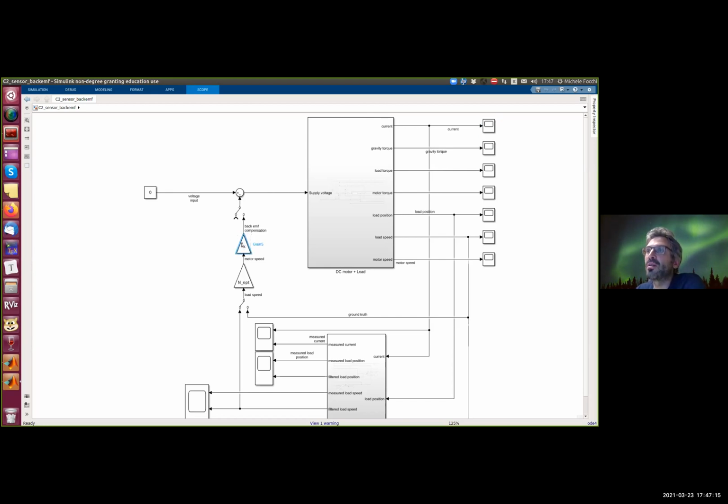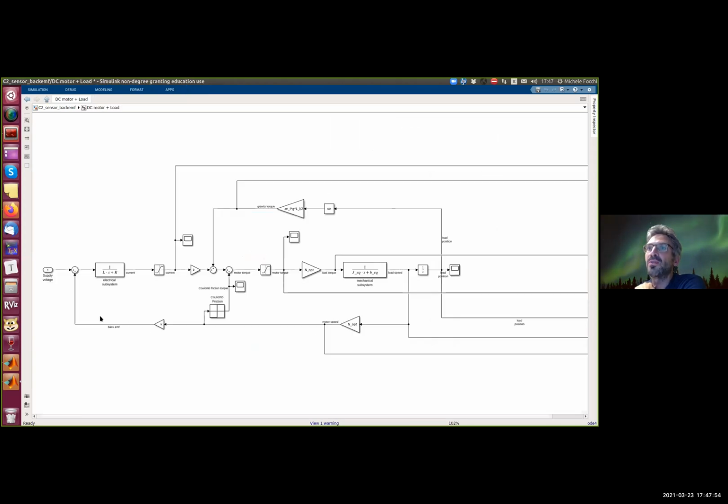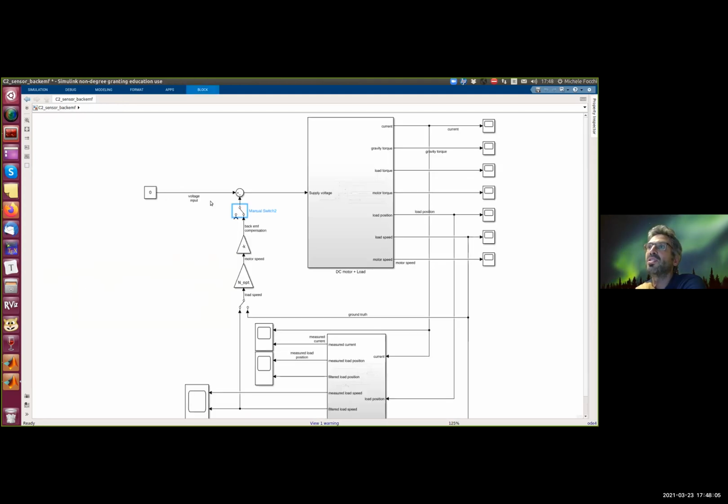And of course, why is there a minus sign here? Sorry, the back EMF was with a minus sign, so we want to subtract the back EMF. If we do that, we apply a voltage that is subtracting the action of the back EMF. This will cancel out this feedback, because we are summing something that is the same as this, so we cancel out this term by applying a voltage that is opposite.